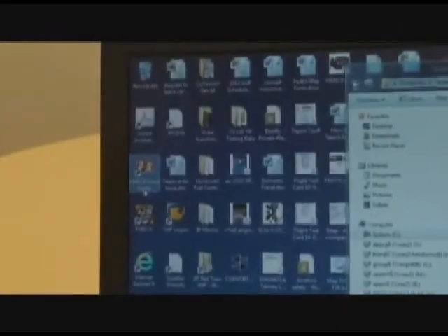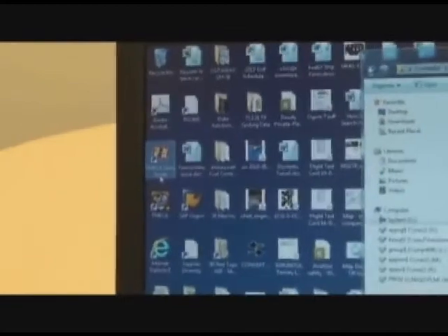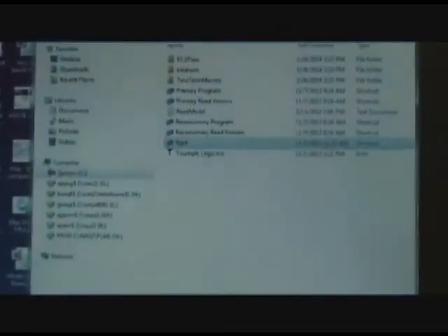Once you're done with that, we'll exit from maintenance terminal again, File and Exit, and turn the power to the ECU off. And now you're done with the loading and verification of the software, and you can disconnect the equipment and put all the pieces back together on the aircraft.